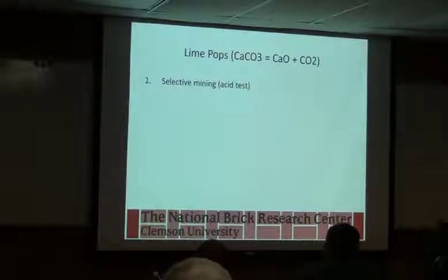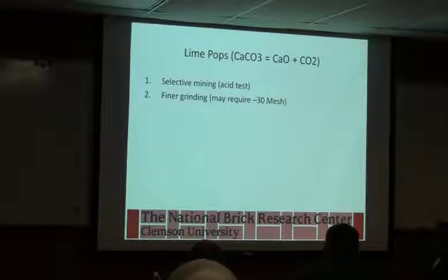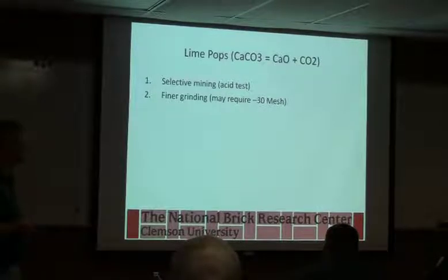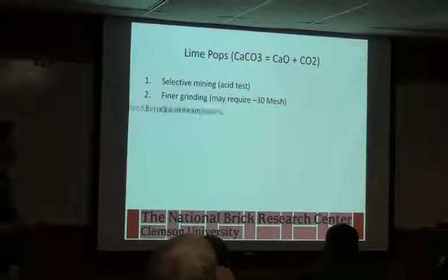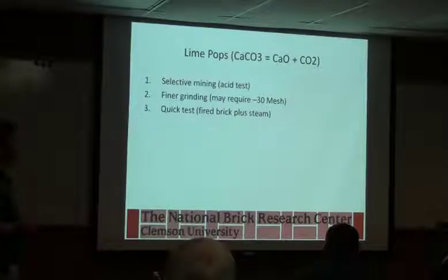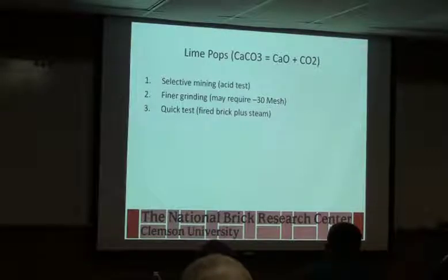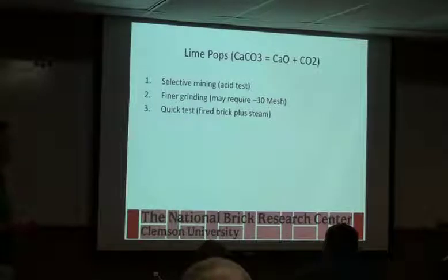Lime pops. Selective mining, or finer grinding. Again, if you have a lime pop and you grind it finer, it's no longer big enough material to actually cause an issue. It'll get distributed in the material. Fired brick plus steam: basically, you're just looking to see if you can get it to pop beforehand. When you put the steam into it, you're trying to get the lime pop to grow and actually erupt.